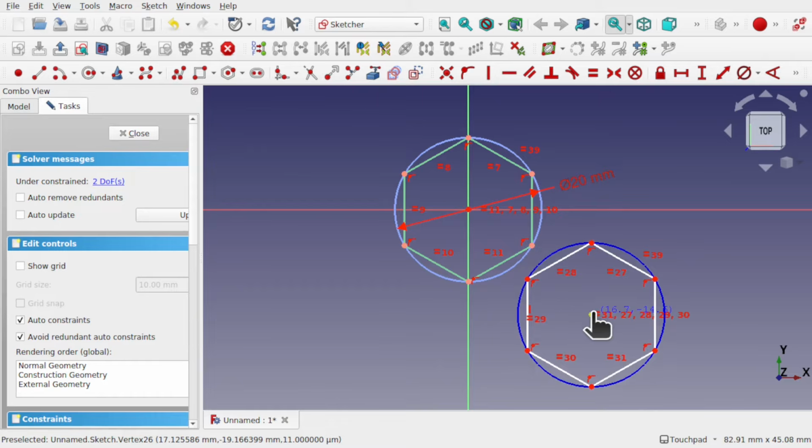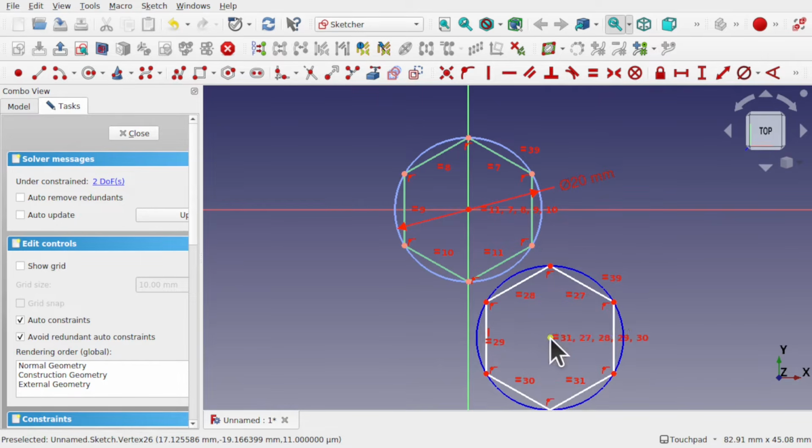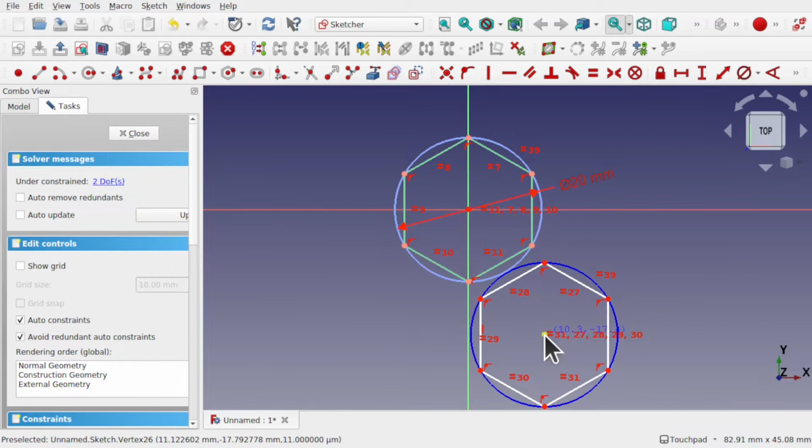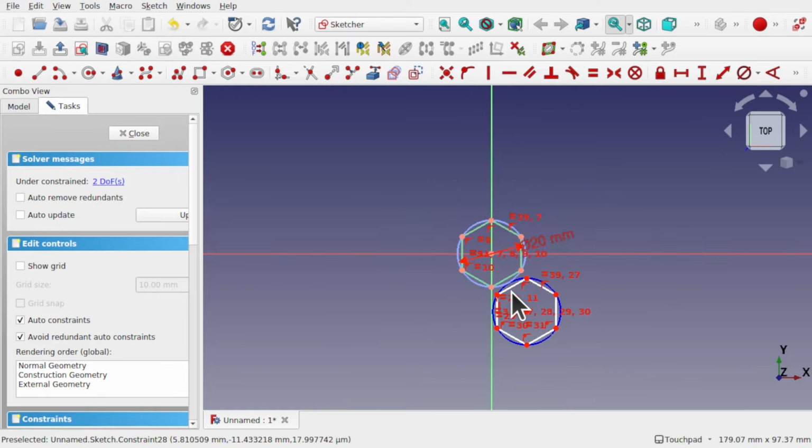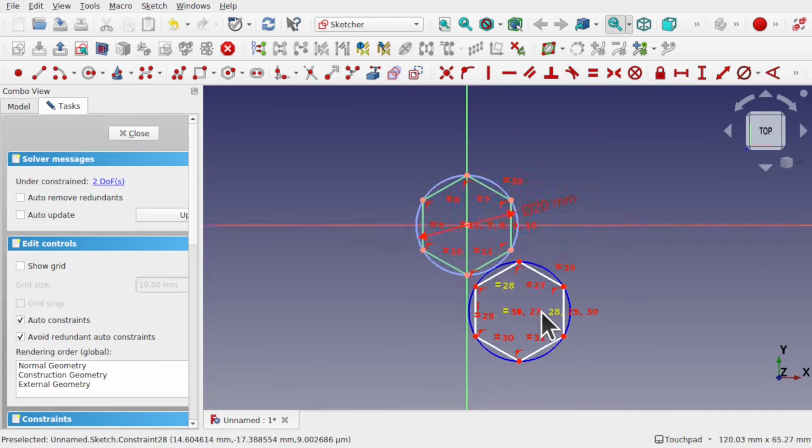Now I've got to constrain this down and also set some distance for this to be away. We're going to stagger them like so. So when this is repeated, the hexagons will fit together. If we think about this and it's repeated down here, they will actually slot together. And if we place them in an array across here, then we build up a mesh full of hexagons.